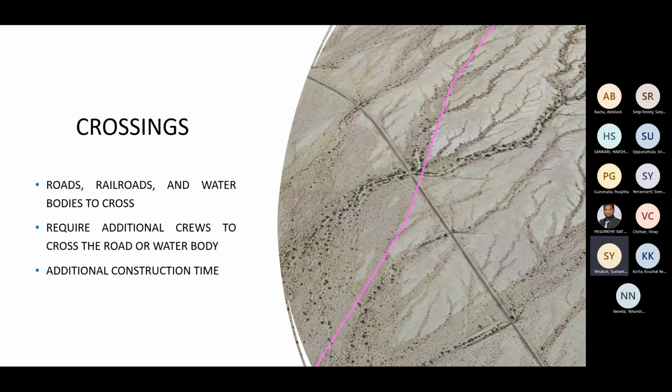So for the project, we have considered different types of crossings. The first is a two-lane paved road, which we use when additional burial depth and more construction design factor is required. The other one is greater than a two-lane paved road, which is used when boat crossing or move around is required. And if it is a 0 to 50 feet water body, we are going to use this when additional depth and protection of water quality is required.